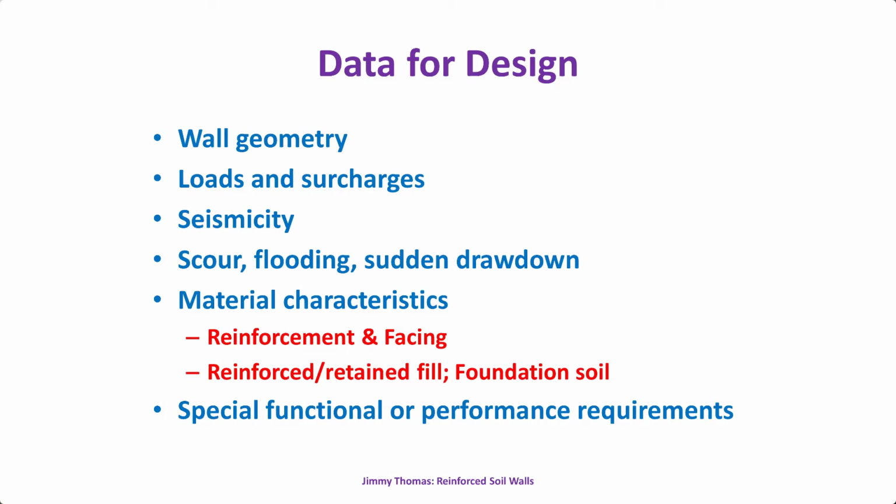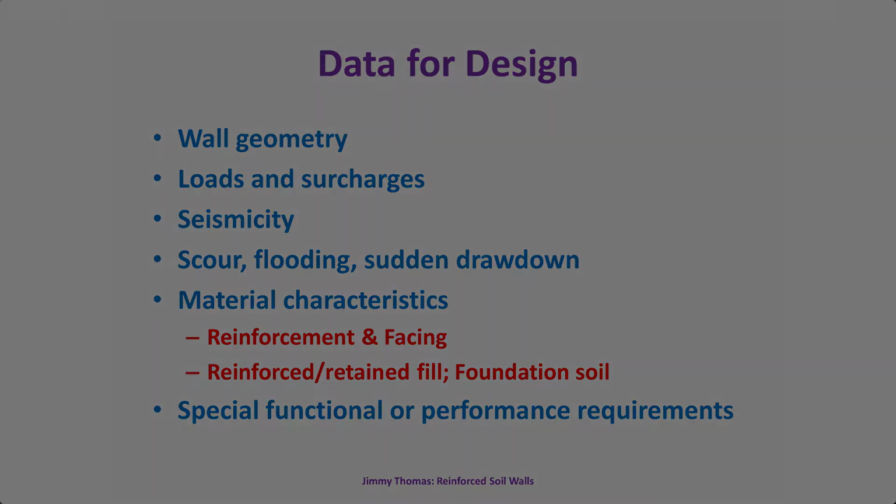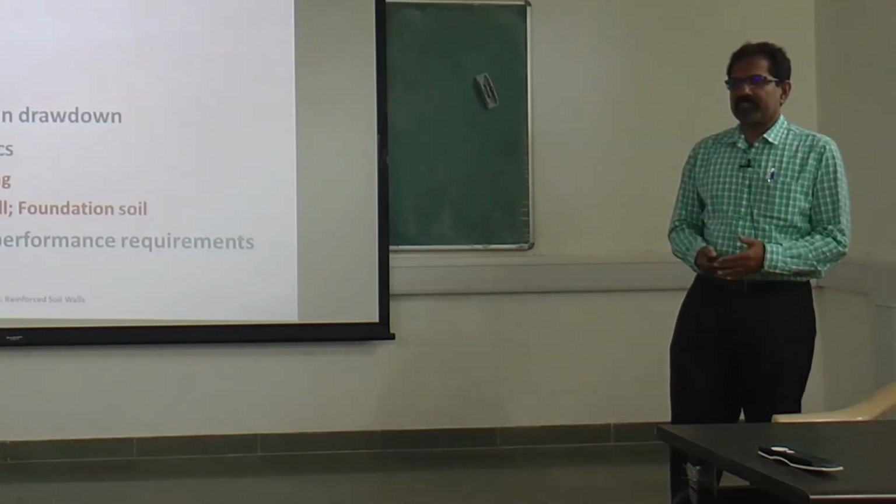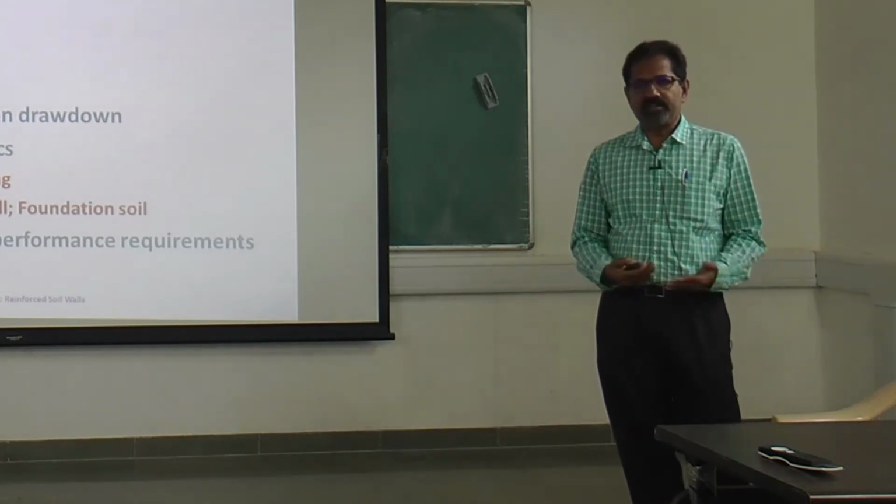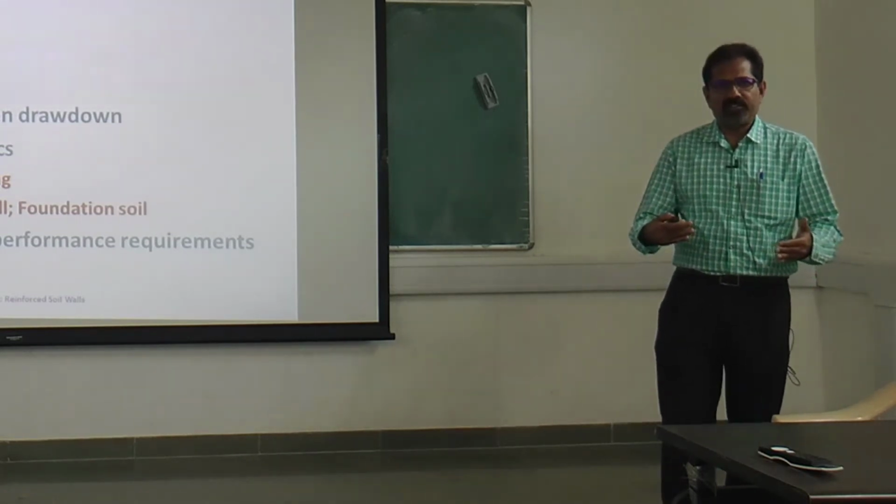Then here, this part is also very important. We have to do the geotechnical investigations up to the required depth. Then there could be special functional or performance requirements, like a bridge abutment, or the wall is supporting a footing.